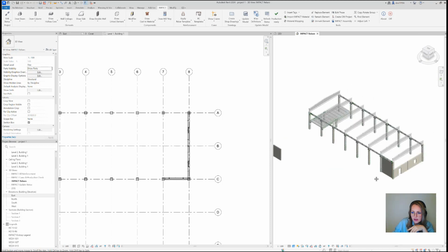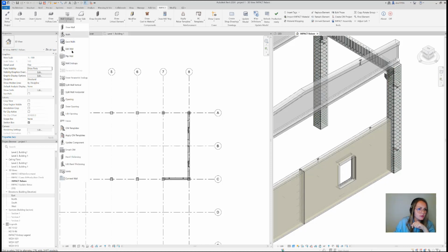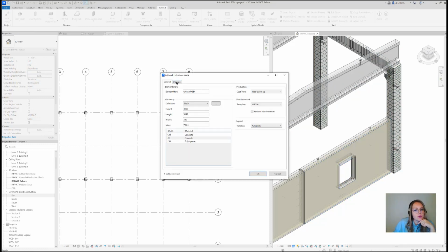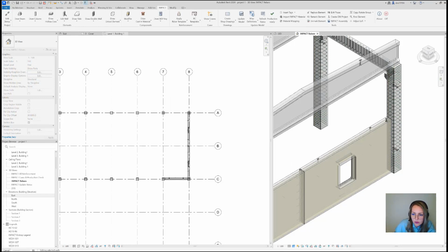We're gonna go like this, and I think we can do it directly in 3D view. So first of all, I need to take the in caps for this wall. So I go to edit wall, and I need to see, if you remember, we've added an end cap here around the roof. So on the left side, I'm gonna need this 807 that was just reviewed. Okay, it's just defining the geometry, pretty basic end cap. We keep it simple right now. Okay, so this wall has an end cap 807 in here.